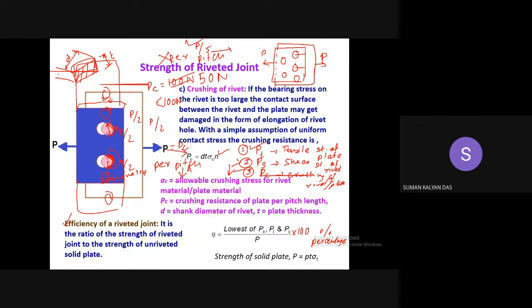Now if we can decrease this uncertainty, meaning the material is perfectly made with all the material processing units operating perfectly, the material has no defect, and the loads have been perfectly calculated with all the analysis and experimentation, then if my estimations are perfect, I will not totally eliminate the factor of safety, but earlier, in the same application, I was taking a factor of safety of 5 because the system was full of uncertainties. When I have decreased my uncertainty, I can perhaps bring 5 down to 3. That is what I am trying to say. Understood? So if I increase reliability, I can reduce the factor of safety, and this is the philosophy of aerospace. In aerospace applications I need to decrease the factor of safety so that my weight comes down.